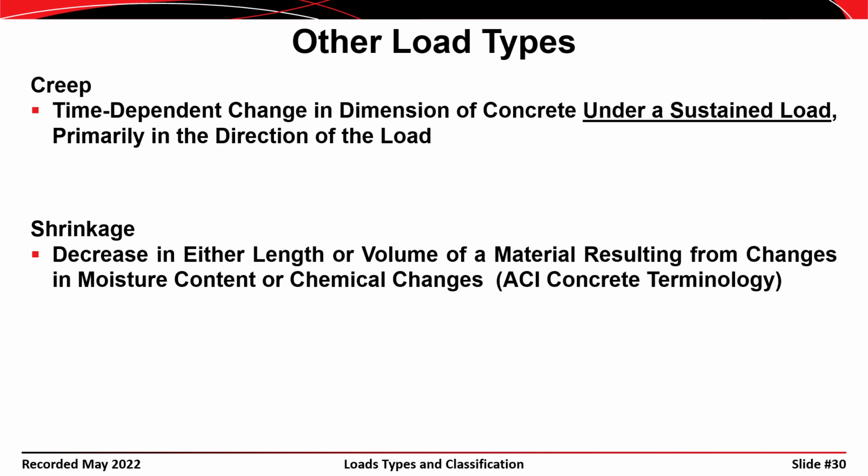So when concrete cures, it's a hydration process. The moisture content of the concrete changes, and it causes the length or the volume to decrease in the concrete. If you don't account for these or accommodate them in some way, creep and shrinkage forces can be appreciable. I know that to be the case, particularly for bridges.